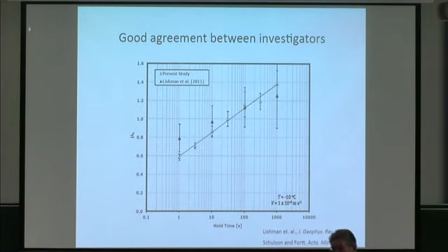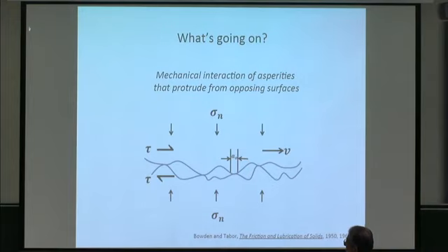The agreement between laboratories, at least 2 laboratories here, I would say is good. Here's Leishman's results, taken a little before ours, placed upon results obtained at Dartmouth, and I think you can see that the similarity is a whole lot greater than the difference. So there's some universality in terms of this behavior, if you wish. So what's going on to describe what we call static strengthening?